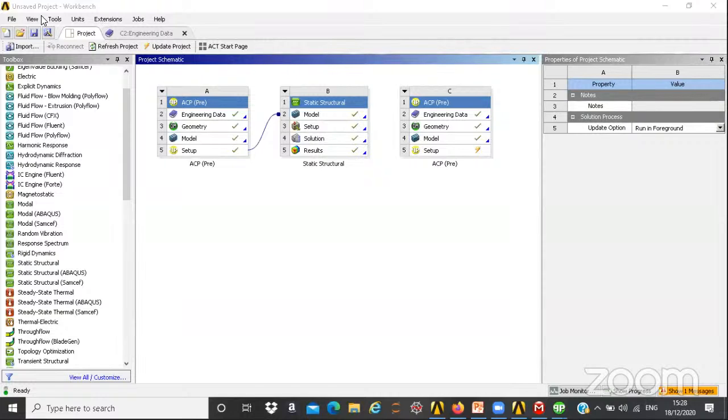What we generally do is, we have the input and output values, and we have a mathematical model like regression or through Taguchi or so many ways. And then we say, this is how we establish a mathematical relation between inputs and outputs, through second order or first order, whatever kind of equation. And then we can optimize it, and this is the minimization or maximization problem. So these are the parameter settings at which you get the minimum surface roughness, maximum tool wear, those kind of things. But when we put it in industry, it is the other way around.